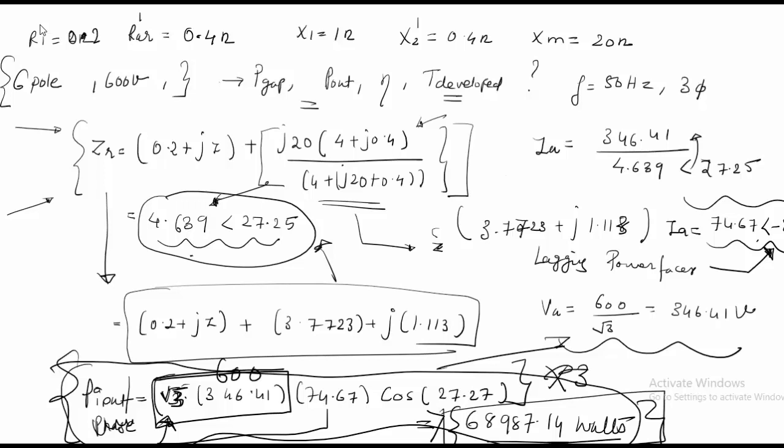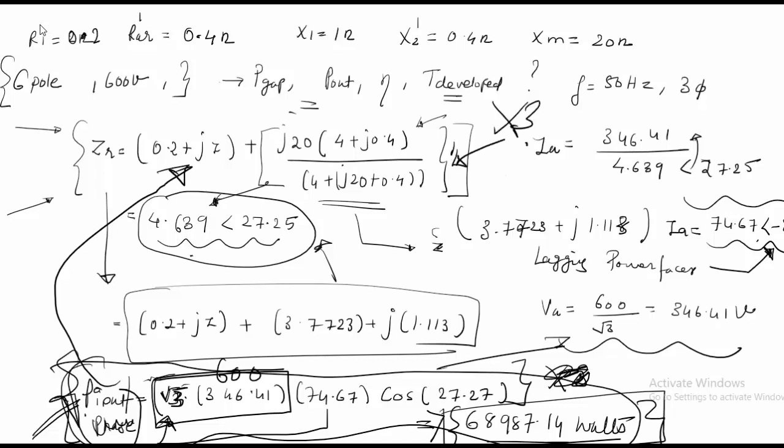output. So if you are calculating the per phase value, then this is a value per phase, since we are only considering the power input per phase, because all our values here, if you see the impedance or the resistance, everything is considered per phase. If you are multiplying even this by 3 and then you are considering all the values, then you will have to multiply it by 3 here, so that will give you the total power input of 3 phase.